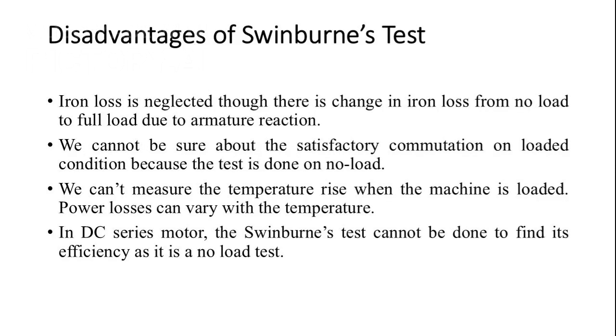However, Swinburne's test has some disadvantages. It neglects iron loss changes, cannot ensure satisfactory commutation on load, and does not measure temperature rise. It is also not suitable for DC series motors.